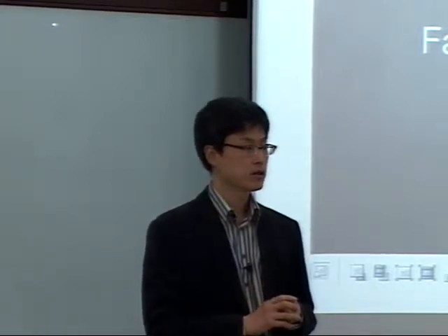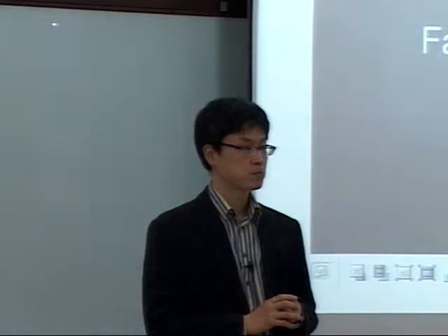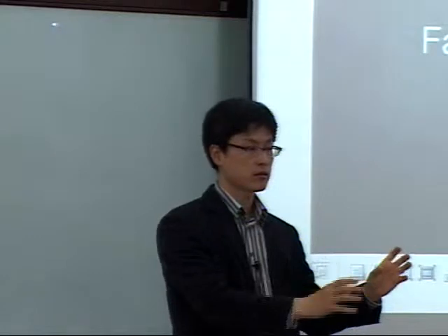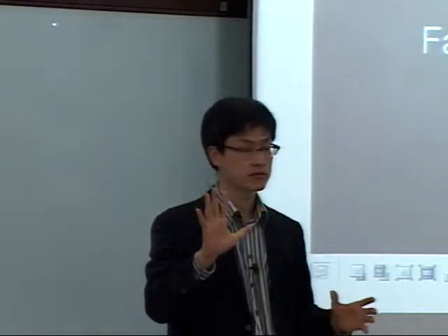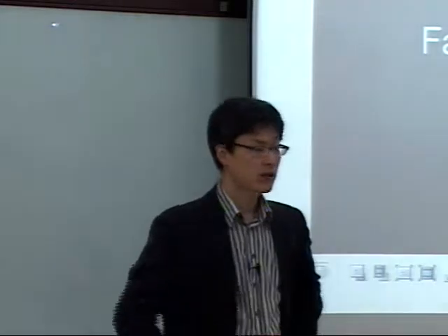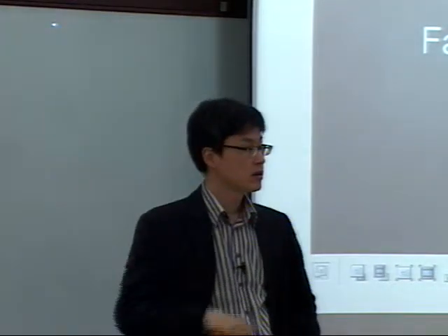For example, if your manufacturing system sequentially consists of five different workstations, and by close observation, workstation number 3 does not add any value, then the most important activity you can do is totally eliminate number 3.